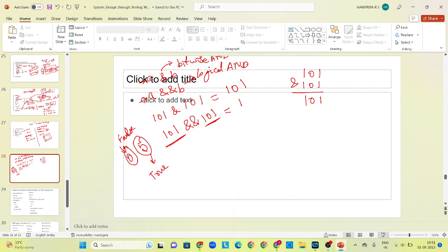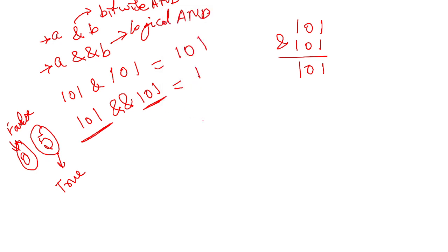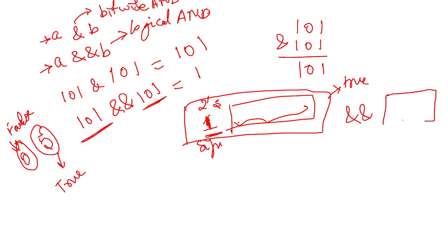Yes, negative numbers we will be representing in 2's complement form. So the MSB bit only will be having 1. In 2's complement form, the MSB is the sign bit, which is 1, and the other bits will be considered as the magnitude. So again it will consider this complete thing as true. If a number starts with 1 also, any number other than 0 will be considered true, because for positive or negative only this MSB bit will be different.